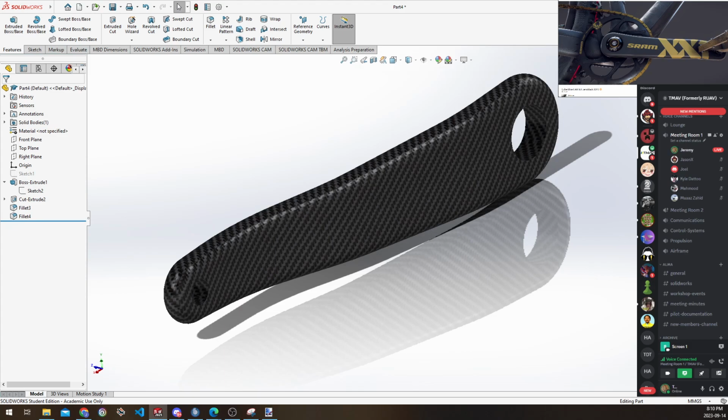It'll be very close. M3 and 1/8 inch are 0.1 millimeters off from being the same size, but they'll be ever so slightly different. And there are tools in the CAD software that you can use to detect issues like that, even when it may not be visible to you that there's an issue. But yeah, tools like that will be very beneficial for you.